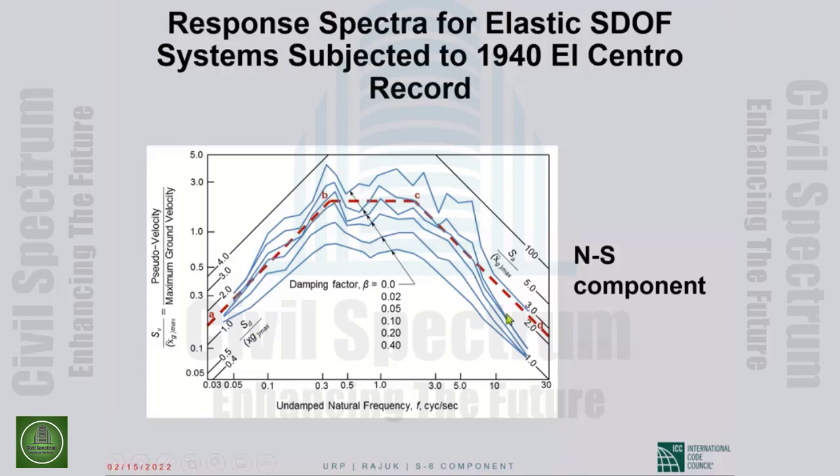You see on this diagonal scale, where we are reading the spectral accelerations, they are normalized with respect to the peak ground acceleration. One important observation, in addition to the fact that the 5% damped spectrum can be represented by the 3 lines, is that along the constant acceleration part of the spectrum, the spectral acceleration is just about 2.5 times the peak ground acceleration.